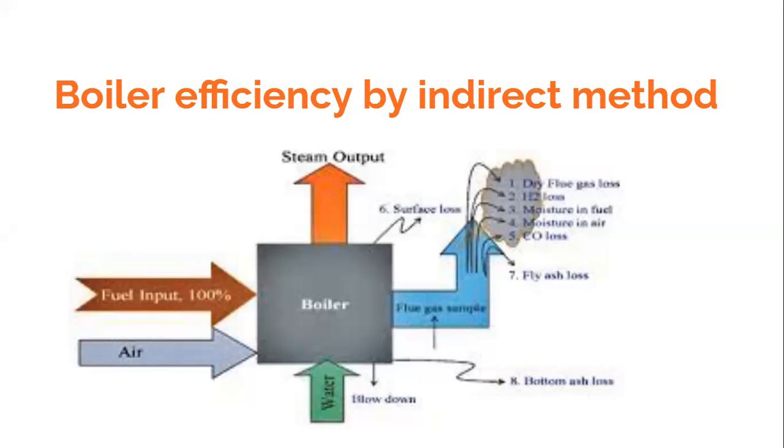If you are doing an audit for estimating the energy consumption of the boiler, you need to just stand in front of the boiler, take a reading of the pressure on the pressure gauge which is provided on the boiler, and read the temperature shown by the temperature indicators, which we have discussed are connected to thermocouples. A nice reading of the temperature of the steam, pressure of the steam, and the temperature of the feed water would help you calculate the output of the boiler. And how do we do that?